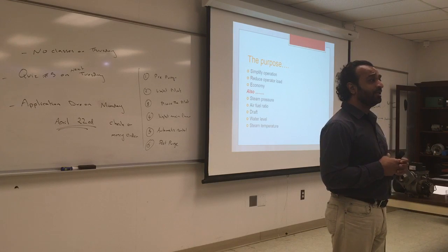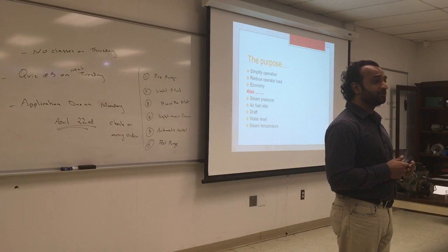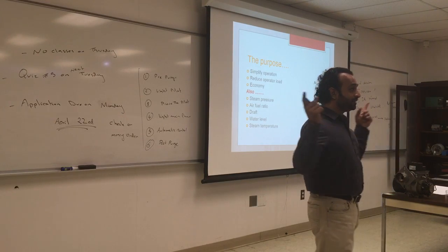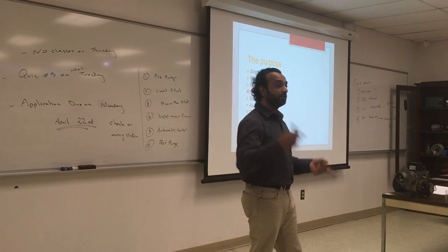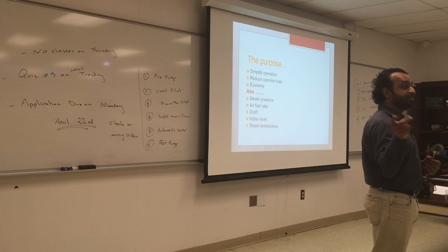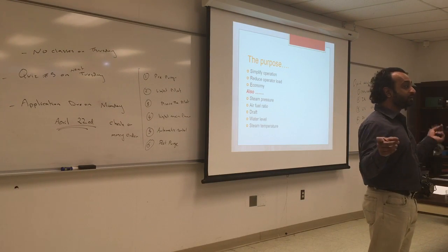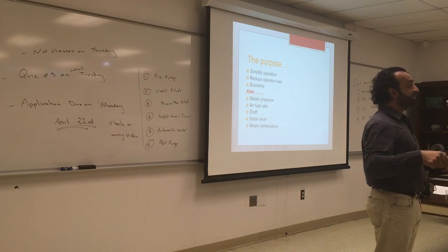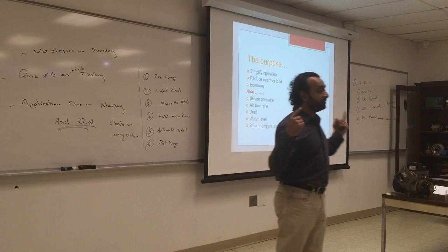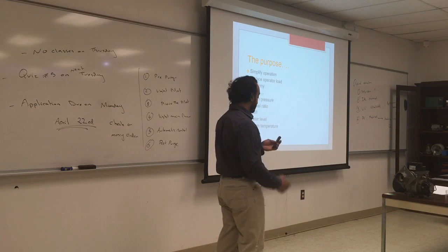Here's a general rule. Before and after any big gasket or valve, you put a pressure gauge before and after, and you send sensors to the control room. That's what the person in the control room does. He monitors all those pressures, and they set an alarm. If this pressure goes lower than this one, sound an alarm, because that means there's a leak. So this is how you know how much you send and how much you receive, and if something is missing, there's a leak at some point.